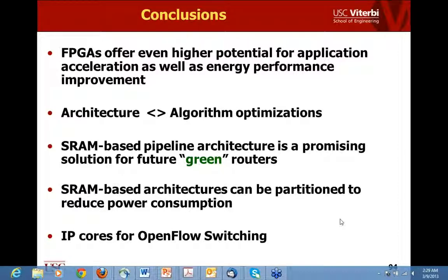So if you had an ASIC device and you changed the regular expression, I could not have done that. So for the third problem, I am exploiting the FPGA programmability, through static programmability, as an expression is given to me. For the other two, you could have done the same thing on ASICs too. Thank you very much.